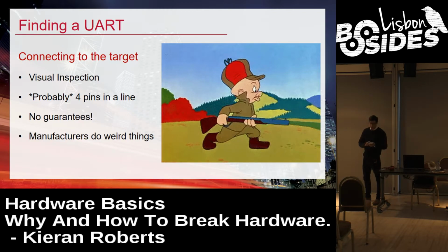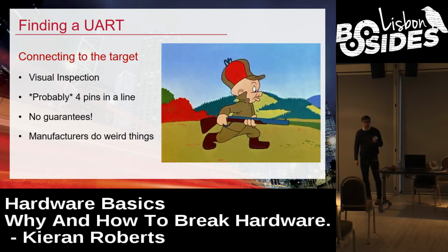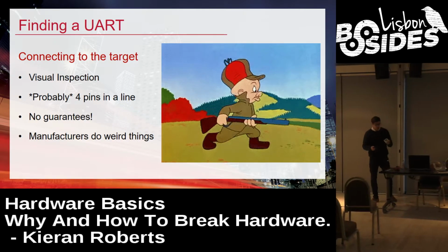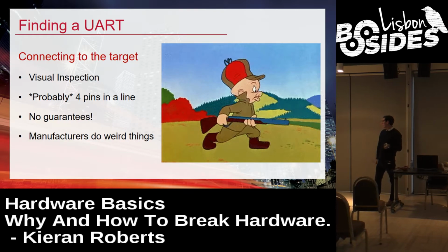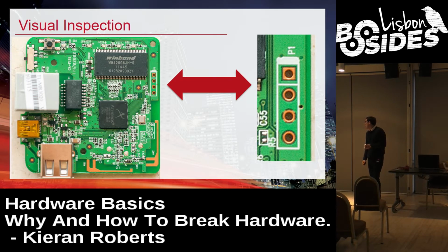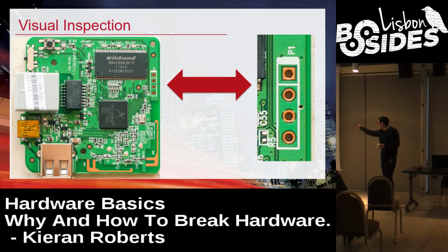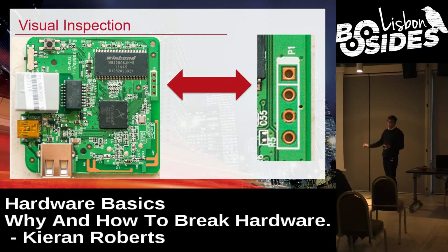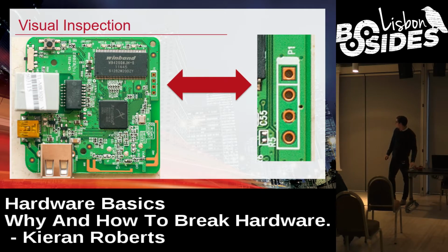So this is a device that's just like a travel router that I had lying around that was going to be like a poor man's Wi-Fi pineapple, and it ended up just not becoming anything. So it was lying around. On here you're going to look at this. I got a bit lucky here. This was my first try at pulling stuff apart, and there's a UART port right there, or what looks like a UART port. You have 4 nice pins laid out, and that's a pretty good indication. That's probably the kind of thing we're looking for.